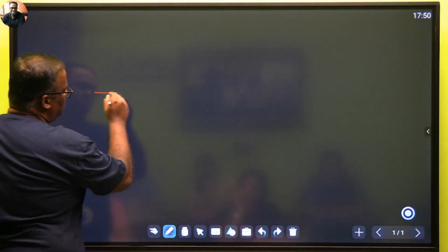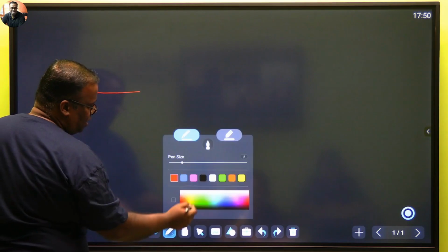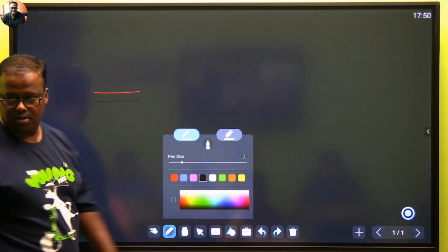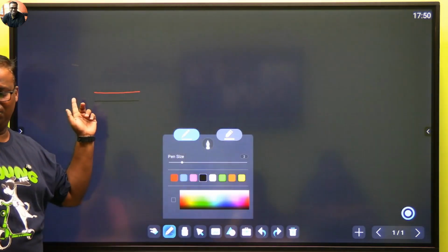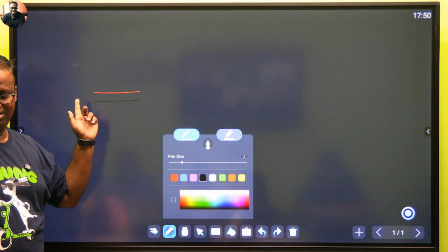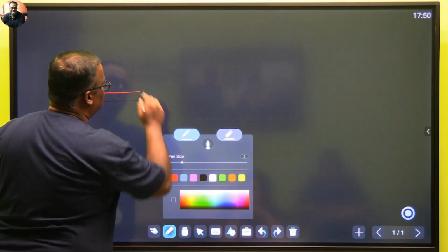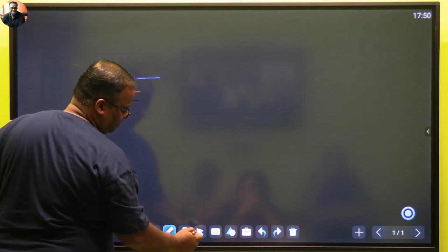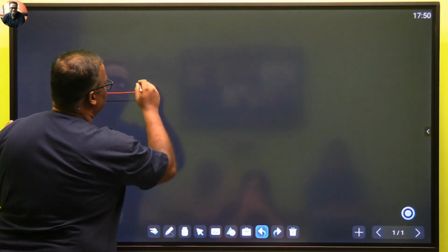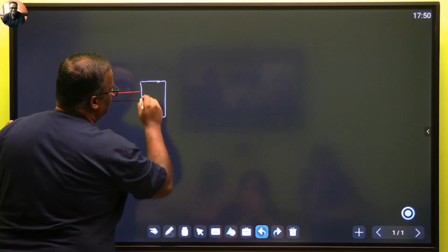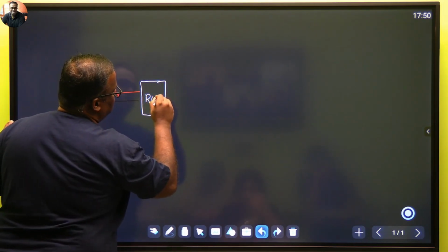So after your meter, this is your phase wire which is coming, and this is your neutral wire which is coming. Neutral wire, the current has to go back. The circuit has to be completed. Okay, this is coming and this has to go back always. So in modern houses, we will have a device out here, and this device is known as an RCCB.